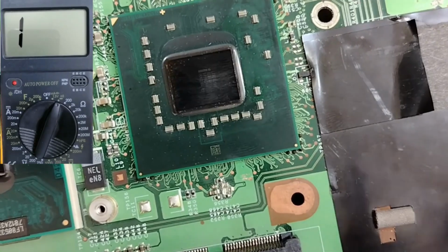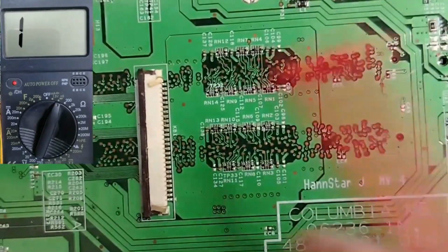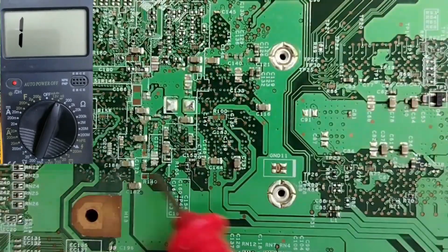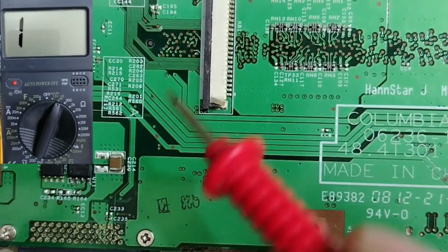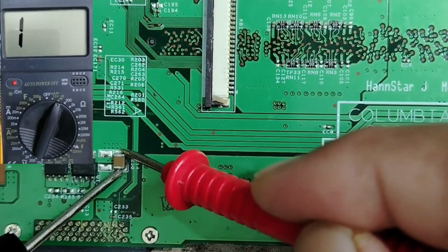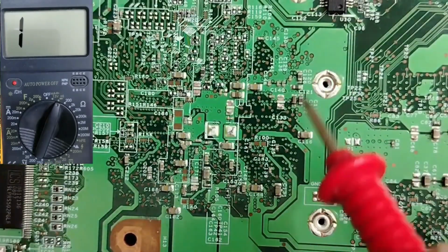But please pay attention to the chipset circuits. Okay, if we go back here, please pay attention. This is very important. Here, this is basically the back of the processor. I told you that for a ceramic capacitor, we should not get continuity, as you can see in the multimeter. So this is good. But we have an exception for the processor.